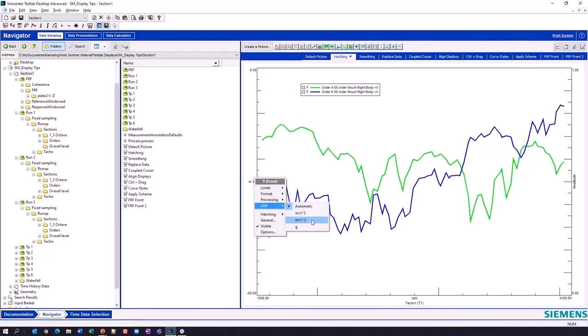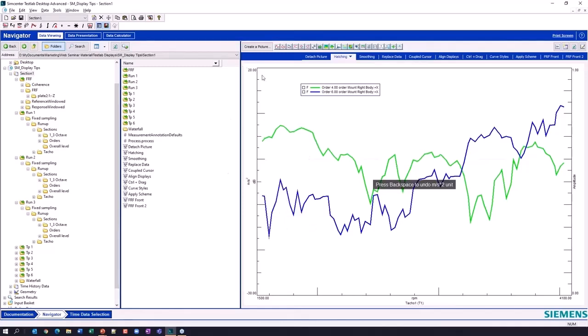I can also instantly look at this same information, but show me acceleration in meters per second squared just by clicking on unit. And now the values on the axis update, and this same information has been converted to meters per second squared. And this is all managed by the units manager for SimCenter, and that runs as a separate application where you can control all of these units and control what units display here and which you'd like to be your default.